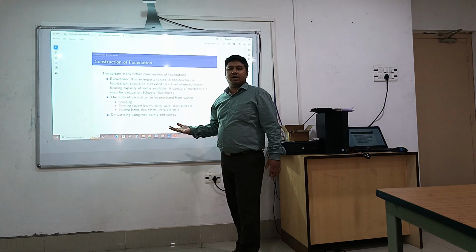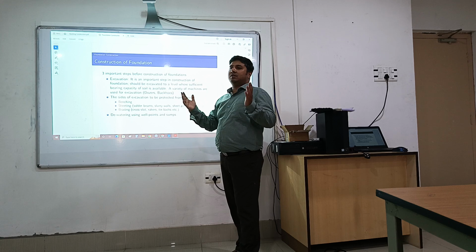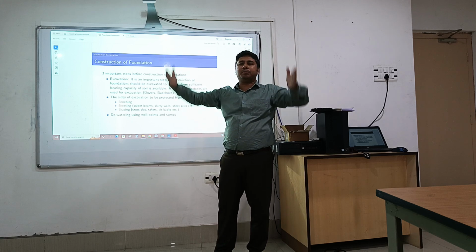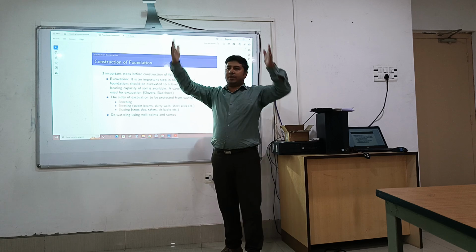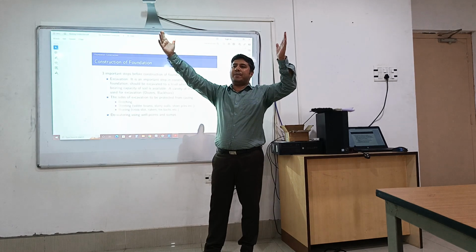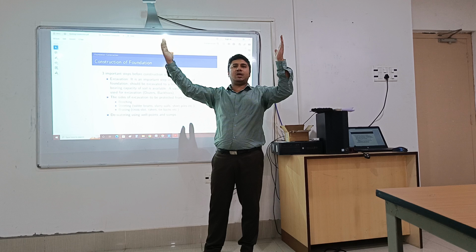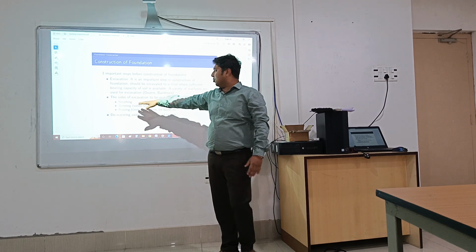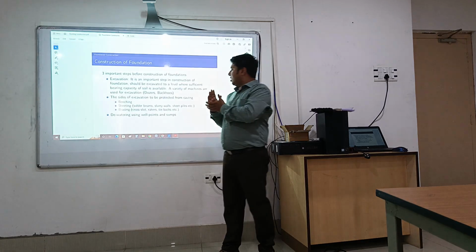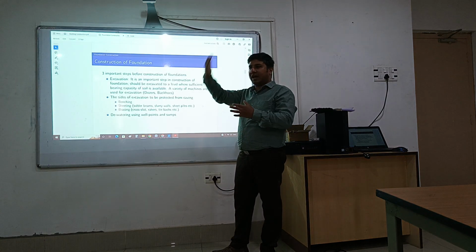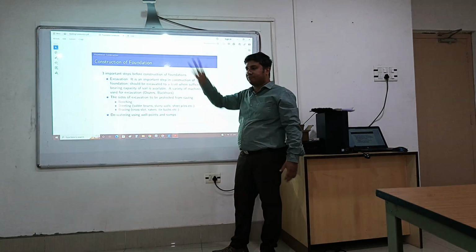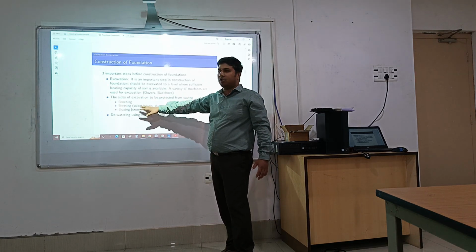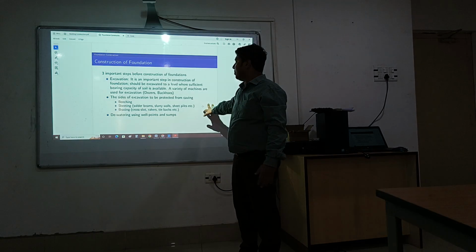After the excavation work is done, due to the earth pressure, the sides of the excavated material may not be able to stay there. Due to the active pressure, they will try to fall. So the side walls need to be protected so that they do not fall, by using measures like benching, sheeting or bracing. We will see all these measures.